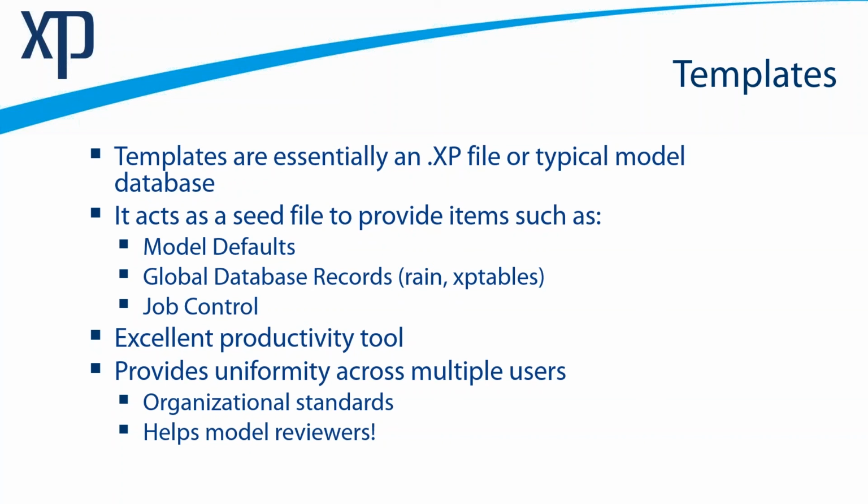So I would say the templates are not only a way to have a standard amongst the organization or the region, but they also help model reviewers. All the models are going to be delivered kind of the same way, with, let's say, green links when they are bioretention ditches or something like that, right? The blue nodes mean it's the combined sewer node, etc. So when you're reviewing, if you're always getting your information presented in the same way, it's easy for you to judge the model's reasonableness and conformity, among other things.